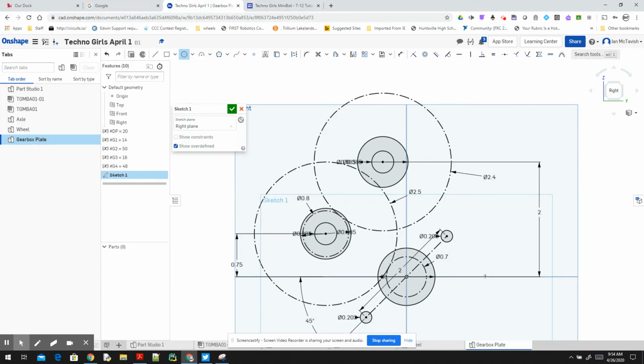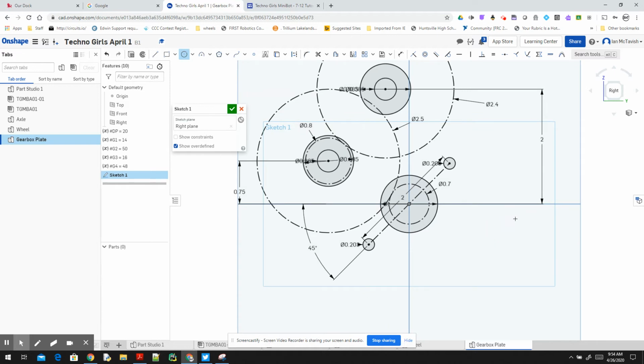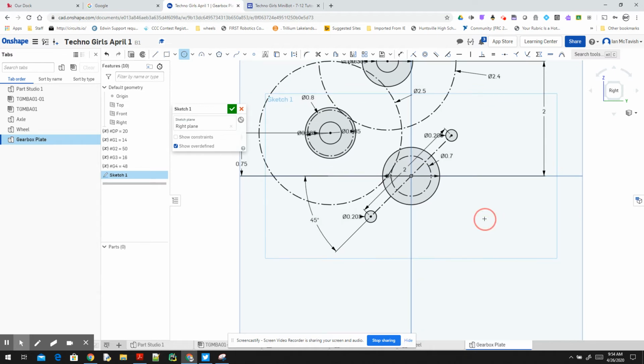And in here, I'm just going to zoom out. So scroll wheel allows you to zoom. Holding the scroll wheel on your mouse and moving allows you to position. So I'm going to create a line. So select the line tool. And I'm just going to go down here and I'm going to click start. Now, you'll notice that I've got the line vertical, I can see there's a little orange dotted line in there and the vertical constraint. So that's perfect because I want this to be vertical. And it's going to be 0.25 inches in length.